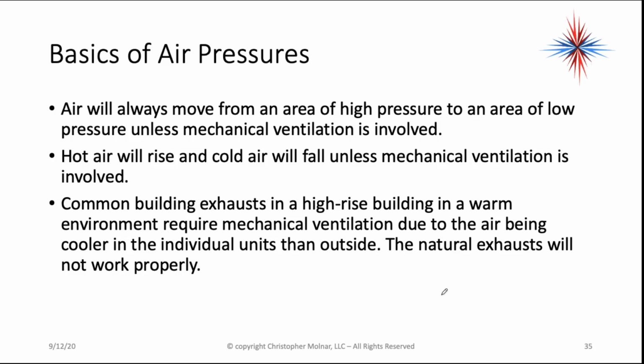Air will always move from an area of high pressure to an area of low pressure unless mechanical ventilation is involved. Hot air will rise, cold air will fall unless mechanical ventilation is involved. Common building exhausts in a high-rise building in a warm environment require mechanical ventilation due to the air being cooler in the individual units than outside. The natural exhausts will not work properly because, again, hot air rises, cold air falls. If I have a 95-degree day outside and my air in the building is 75 degrees, the natural exhaust is not going to work properly.